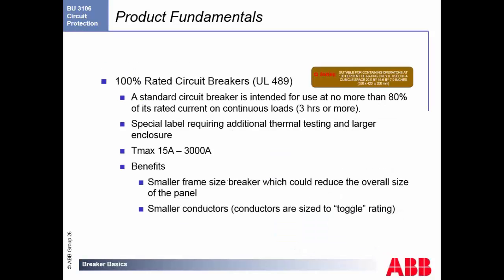We have 100% rated circuit breakers, UL 489. It's unique, which means you can control the loads, which is typically not an application that's recommended for opening and closing that load. So generally, I know it's not the right application, but a lot of people, as they leave their building for the weekend, want to flip one switch and have everything shut down.